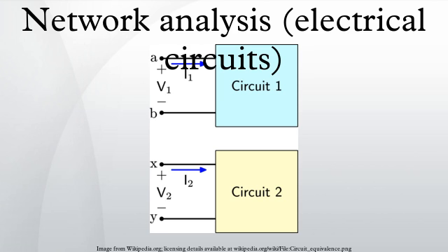The commonly accepted values for the transition point voltage are 0.7 V for silicon devices and 0.3 V for germanium devices. An even simpler model of the diode, sometimes used in switching applications, is short circuit for forward voltages and open circuit for reverse voltages. The model of a forward-biased p-n junction having an approximately constant 0.7 V is also a much-used approximation for transistor base emitter junction voltage in amplifier design.